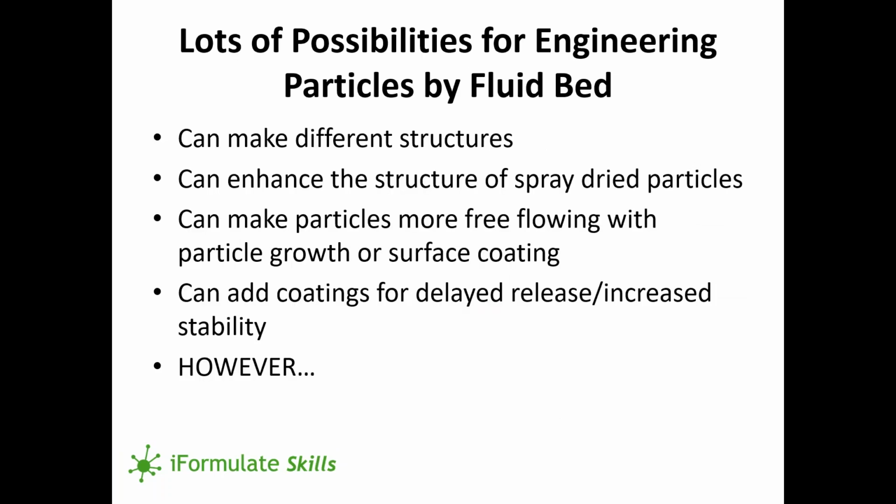So on the next slide, you can see that we've got lots of possibilities for engineering particles using fluid beds. You can create additional structure onto an existing structure. You could even, if you wanted, use a solution or an emulsion to spray onto the surface, which would include microencapsulates, and therefore you could have a core particle structure, and then put another different structure on top of that, and then put a coating on top of that. That ability to keep the particles inside the bed for long periods of time gives you lots of possibilities for playing lots of tunes on the process.